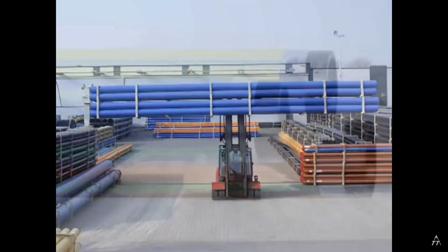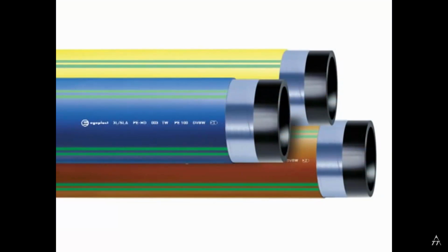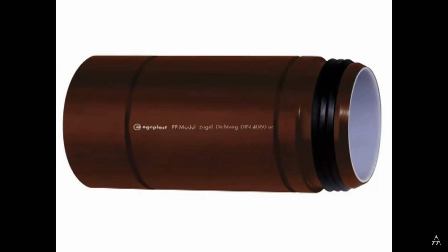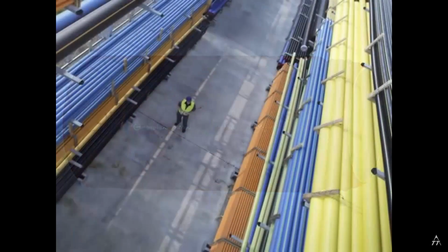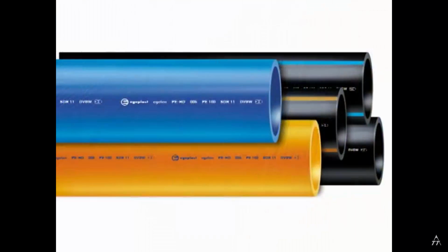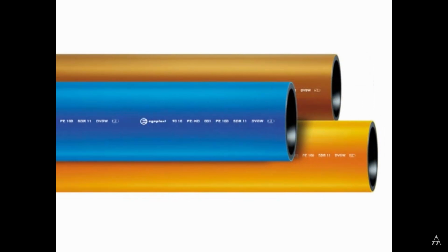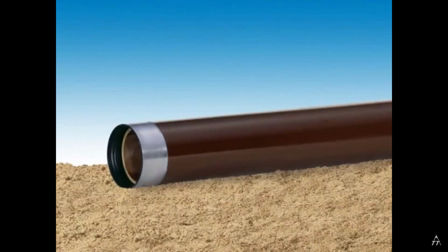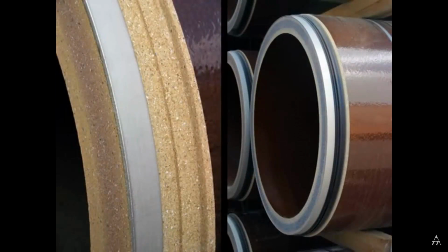Pipe manufacturers have developed pipes with functional protective coatings which conform to the requirements of pipe bursting. Industrially produced and tested pipes, mainly made of high-density polyethylene, polypropylene high modulus of elasticity, as well as cross-linked polyethylene plastic pipes supplied as single or coiled lengths, but also cast iron, steel, stoneware and polymer concrete pipes can be installed.